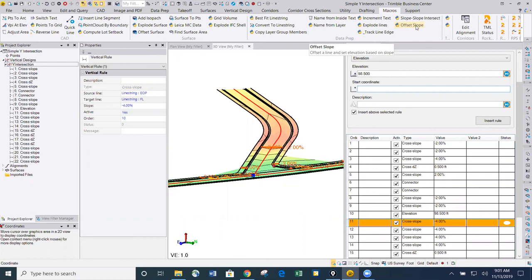The second instruction here is offset slope, and that allows you to take a center line and a slope, or center line and a second string, or two strings, to calculate the cross slope, and then you can project it out at a distance. So you can say, I want to offset by 10 feet or 5 feet to project out a surface. If the surface is super elevating between, let's say, -2 and +4 or something like that, then the projected offset point will also be super elevated by the same cross slope at the offset. And then you can apply a vertical or perpendicular offset to that to calculate an offset downwards. So if you're trying to calculate offset strings behind a back of curb at the cross slope of the pavement, these two tools will be a godsend for you in the product.